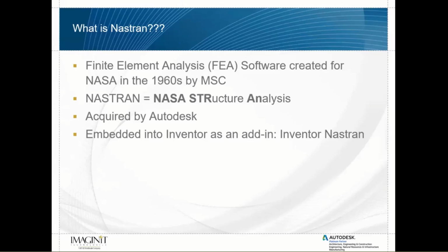So it is embedded in Inventor as an add-in. This is nice because if you are familiar with a tool like Inventor FEA or SolidWorks FEA or any of those other CAD-embedded tools, this allows you to take your 3D model that you're working on in Inventor and immediately apply your finite element analysis without having to export the shape and work in a different software. So you can make these analyses in Inventor, keep your assembly or your part in Inventor, and still continue to use tools like Vault for other product data management software as well.